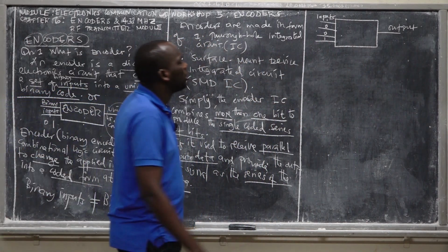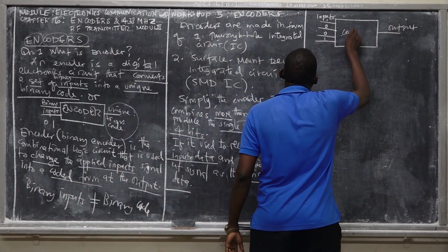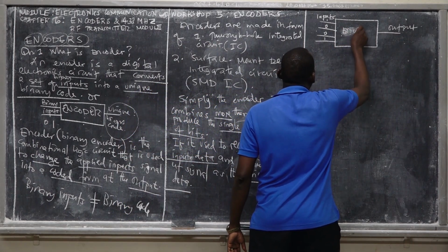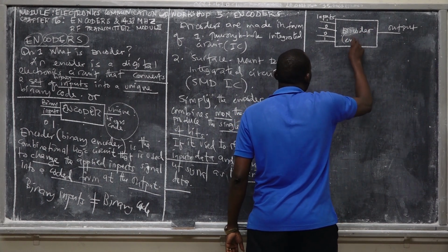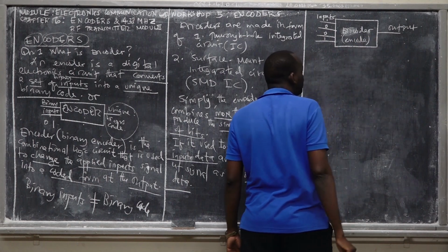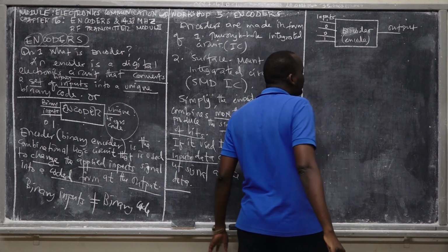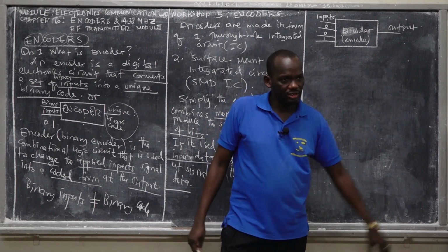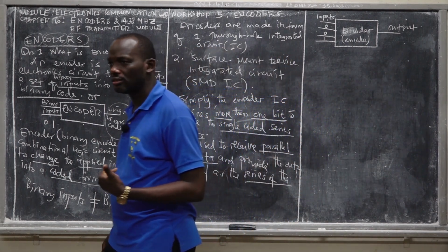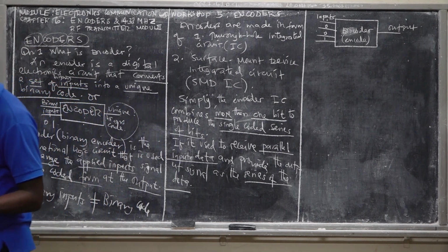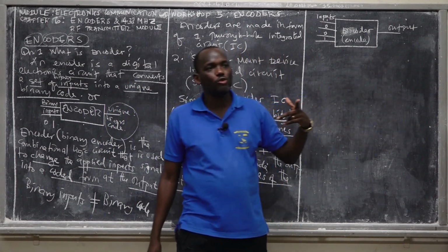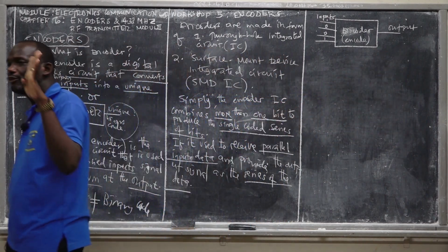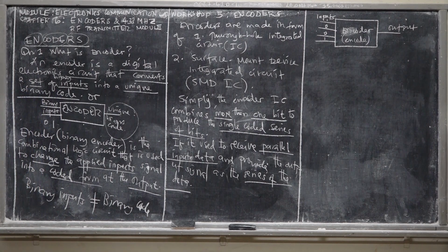And then they'll be processed, or they'll be coded. This is the encoder. So the encoder will code it. Okay? This is the encoder. So the encoder will encode the information signal. Once it codes the information signal, the output stream is just a single one, or there might be two. But remember, whether we have a single output or two outputs, the inputs actually had 4 bits, which are being introduced to the encoder in the form of parallel.